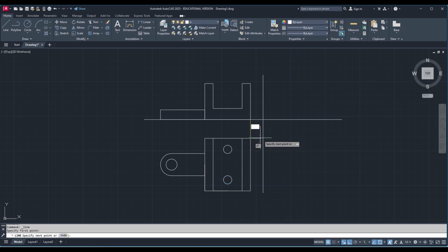Okay, so then I'm projecting, and now the basic top view is over, so I'm projecting and obtaining the basic side view first. I'm matching the property of this projection line color so that it will be differentiated. After turning off the ortho, I will draw this 45-degree line which will transfer my distances to the side view.